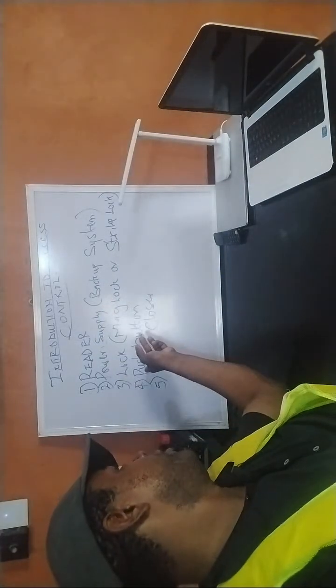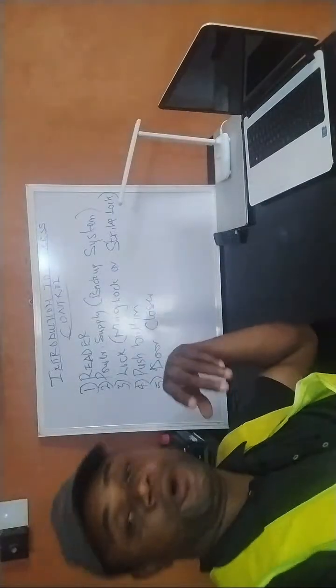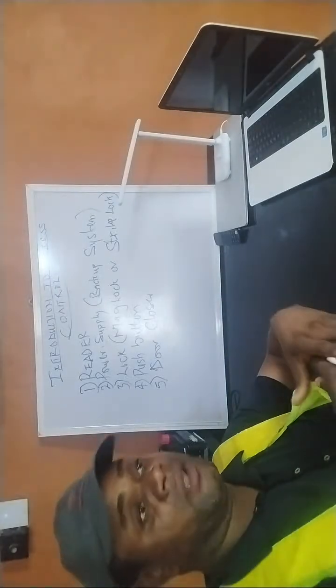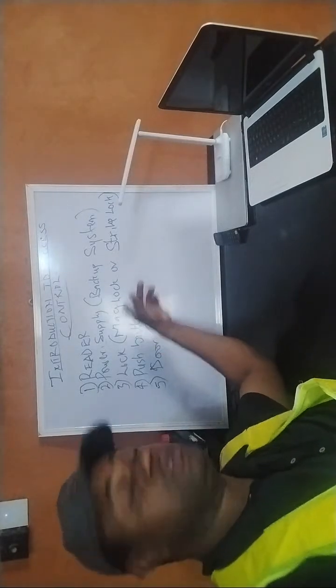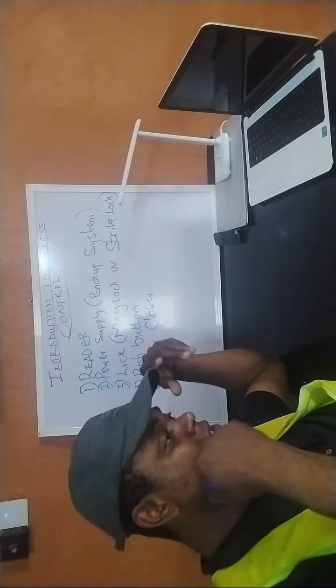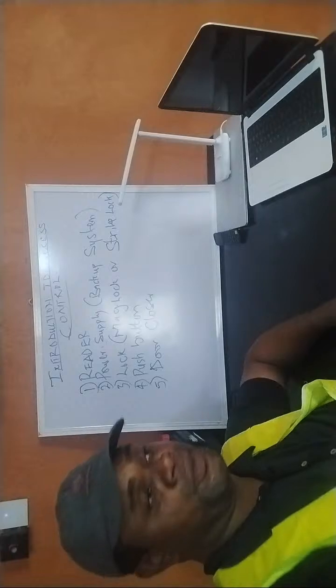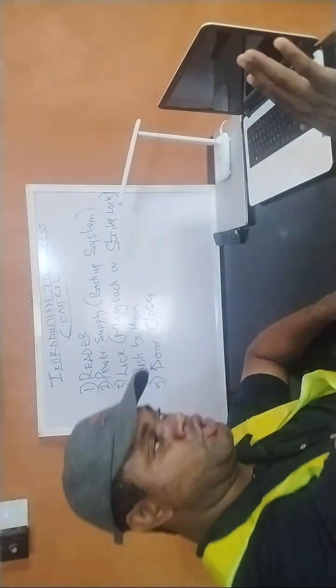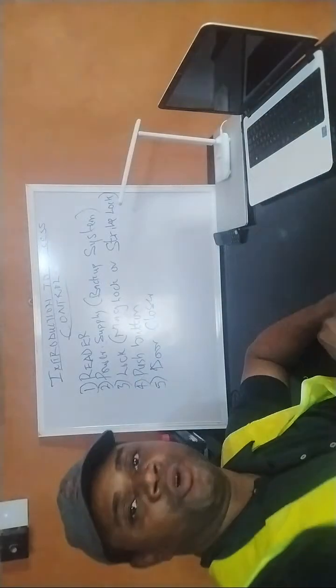Then for the push button, most times you can use either the normally open or the normally closed, but the kind of lock you're using will determine what you're going to use for your push button. And for your push button, there are different types. There are the ones that need a hard push for it to operate, and some no-touch ones. You just take your fingers or your arm close to it, and it opens.